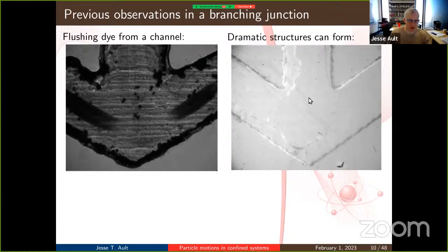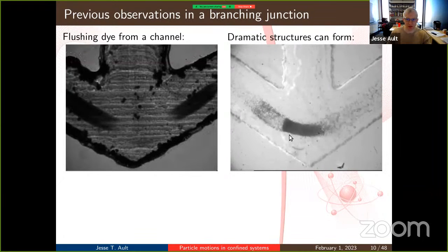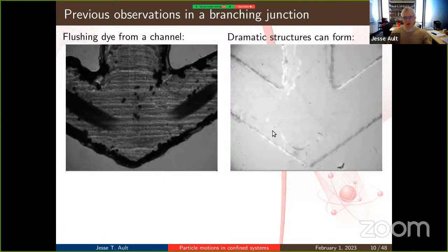And then when you introduce something like bubbles or low density particles, you can also see them accumulate rapidly into these regions, and they'll actually remain trapped here internally, just recirculating as long as you maintain the flow. If you actually increase the flow, trying to flush them out with faster flow, it actually just strengthens the trapping. So you need to reduce the Reynolds number below the point where the vortex breakdown occurs in order to actually flush the system.